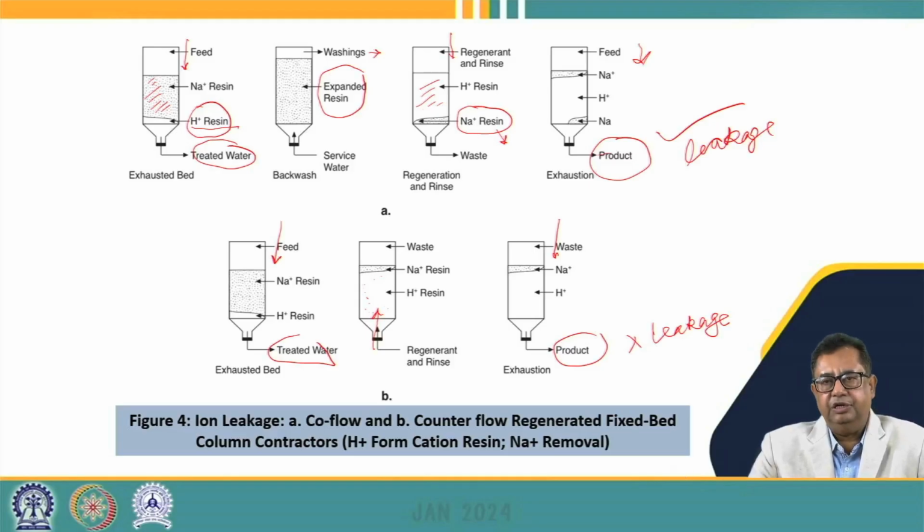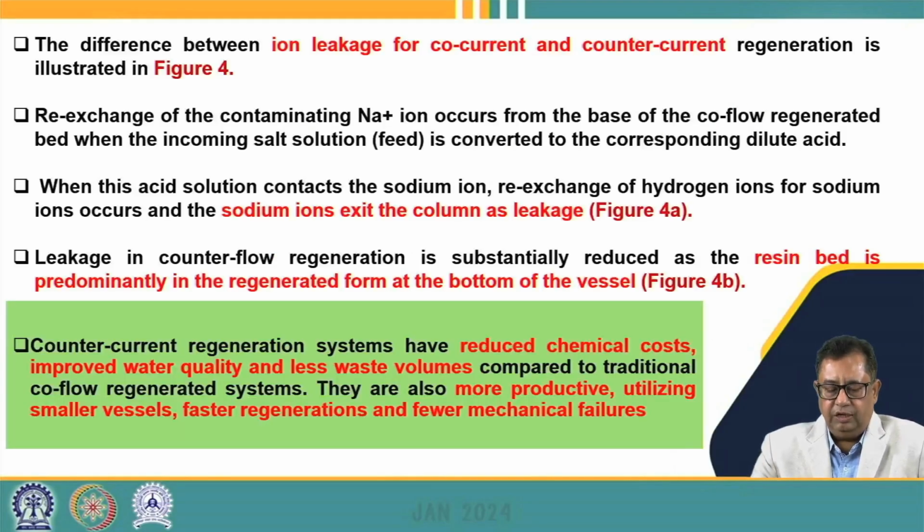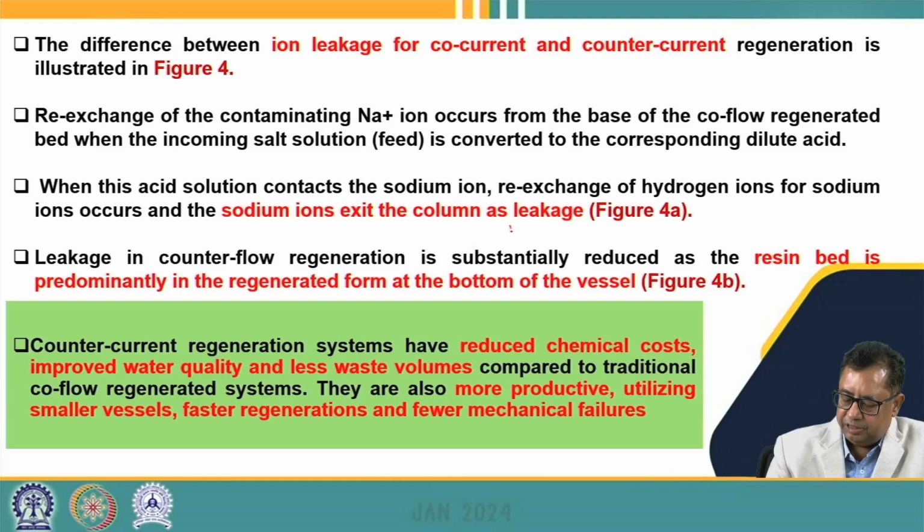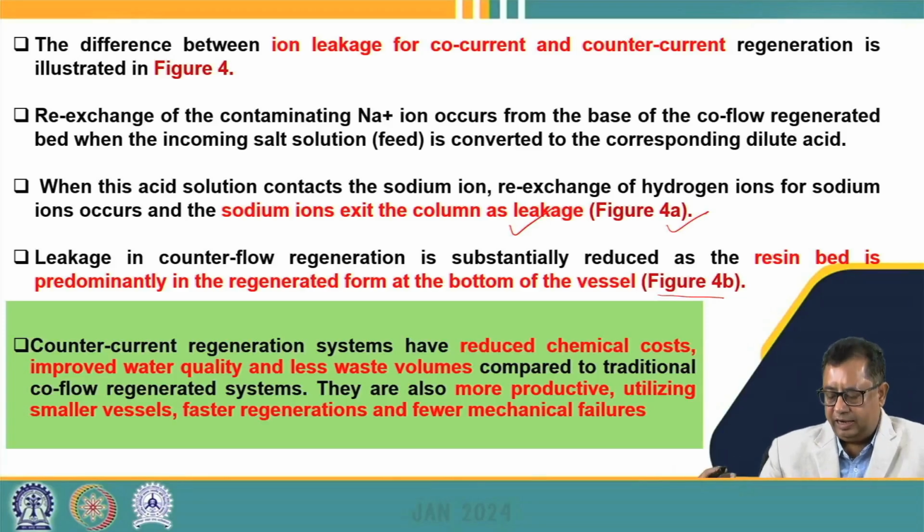That's why we prefer the counter current regeneration. So here we have already discussed the ion leakage, which happens for the co-current and counter current methods, right? We see that the sodium ions may exit the column as leakage, as shown in figure 4a, whereas there is no leakage in the counter current system, which is represented by figure 4b. We see that the resin bed is predominantly in the regenerated form at the bottom of the vessel, because of which less leakage takes place in that system.